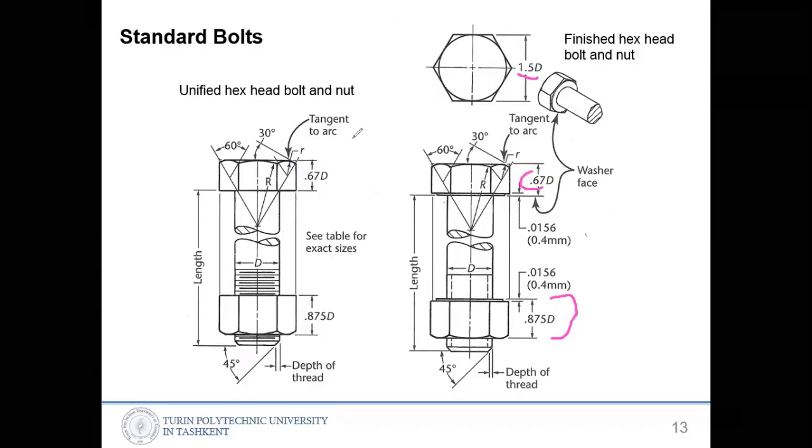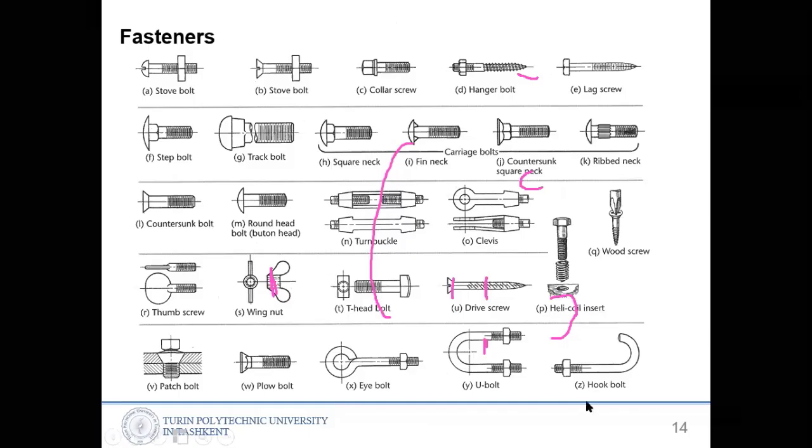And so you have to follow this kind of parameters and drawing standards. So the simplified version of the view is this one, the threaded thing. But that is less simplified, and that is, as I told you, the ANSI standard that is made with a dash line. But in our case, that is similar, but this one is a continuous line. But here you have to continue until touching the tip. Okay, so that is the fasteners.